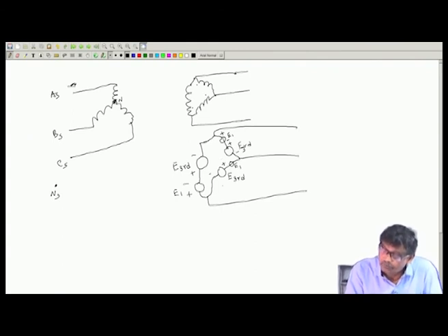Now, in this closed loop, so far as the fundamental component is concerned, these voltages are 120 degree apart, they will sum up to 0. And no circulating current will be able to exist here, because they are 120 degree apart. But what happens to E third component of voltage? They are cophasal. So, when this is minus, this is plus, and have some instantaneous values. Similarly, this fellow has the same voltage, same polarity, and they are connected in series. So, there will circulate a third harmonic current,